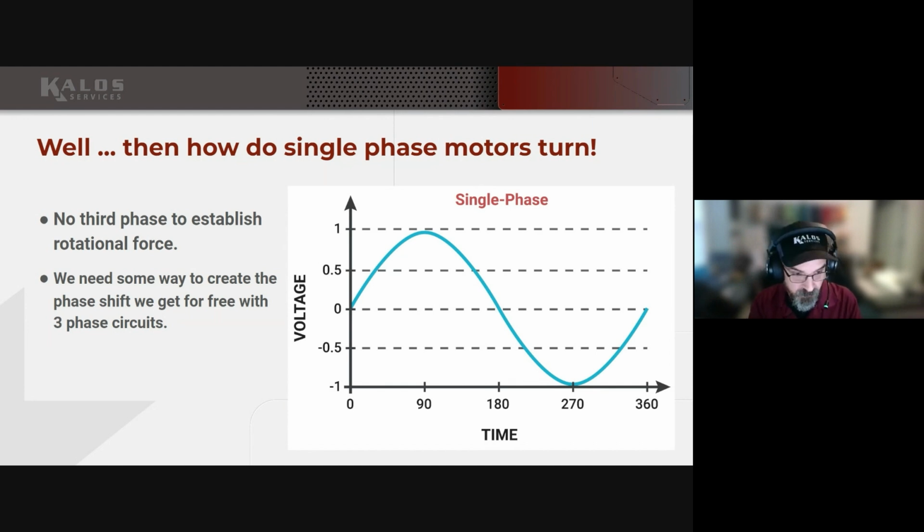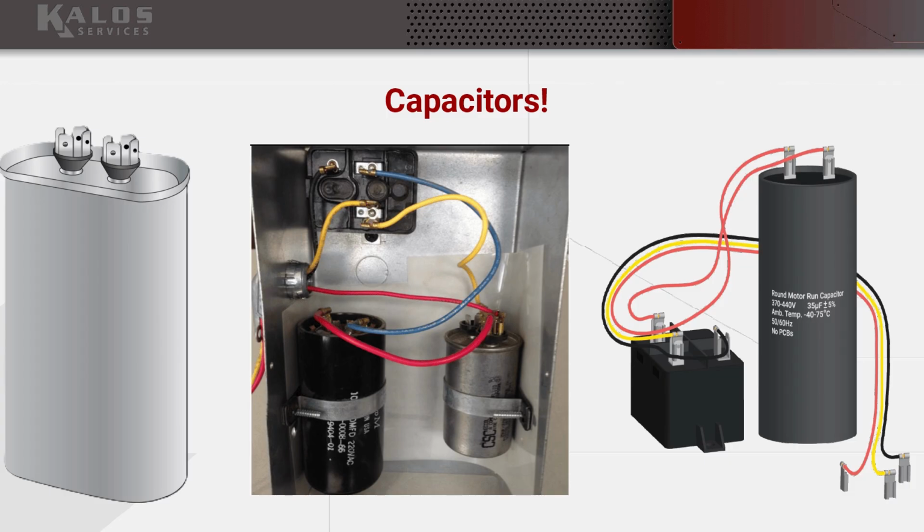And so you can get the two poles that you need out of the three with single phase when you wire it, when it connects to that motor. But how are we getting that third phase? Well, we do that with capacitors.